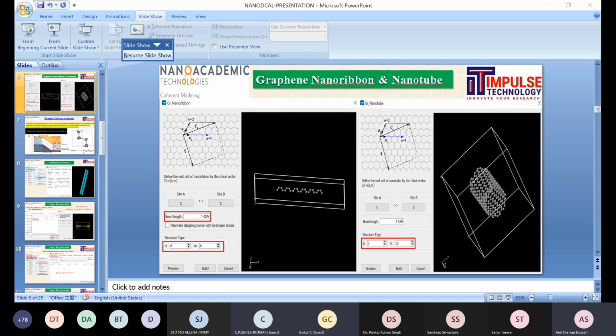Now, if you want to create a device as well, apart from materials or molecular structures, you can simulate FET devices, GNR FET or carbon nanotube based FET devices, and 2-terminal, 3-terminal or multi-terminal devices. The transistor option is there where you can apply the biasing voltage on the source region, drain region, and gate regions, and based on that you can find transport properties, IV characteristics, transmission spectrums, and photocurrent analysis.